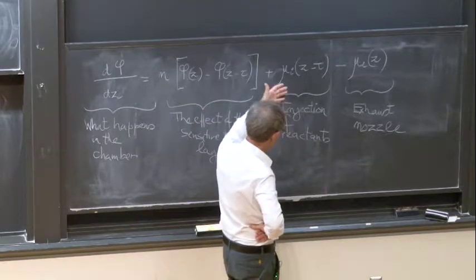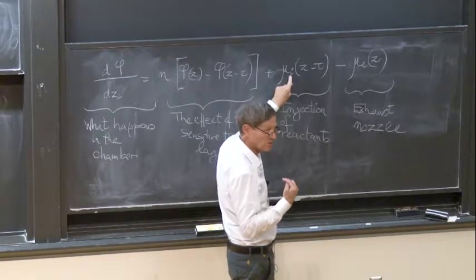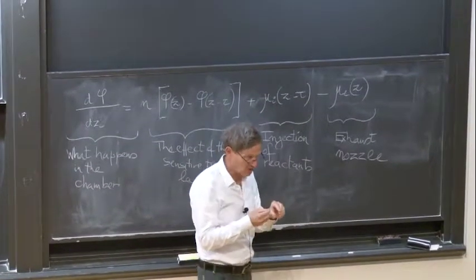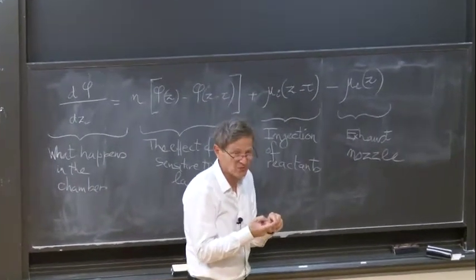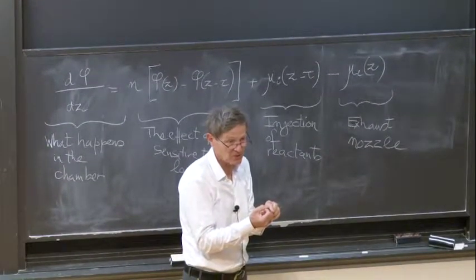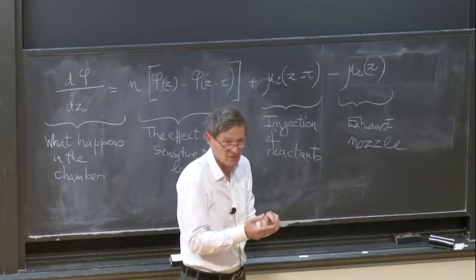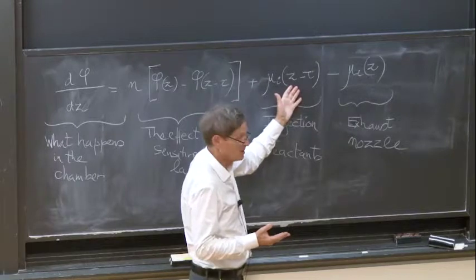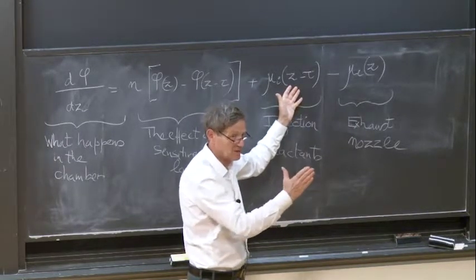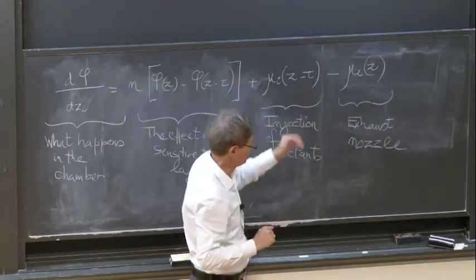Then it is possible that the dynamics can be modified because the injection may itself respond to what happens in the chamber. For example, if you have an injector and you increase the pressure in front of the injector, and if the impedance of that injector is not very large, well, the flow rate will be diminished. So that can be expressed here. And this happens with the time lag. What you inject at t minus tau is what you burn at time t.